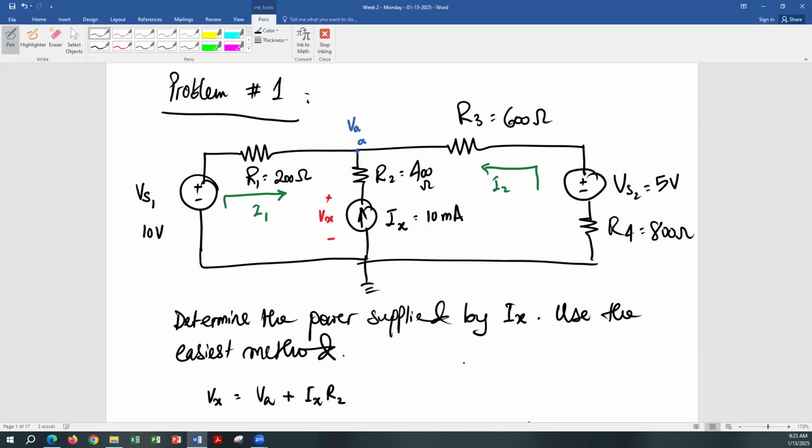So if you're doing a lab, you put the resistor first, connected to the ground, then the voltage supply, then this. It's still going to be the same if you move that resistor up and connect the voltage supply to the ground, because again, it's the same current, remember. If the current splits, that's a different story, right? Then you'll have to consider how you are arranging components. But if all the components are in series, you can rearrange them whichever way you want. It's not going to make any difference, right? So keep that in mind.